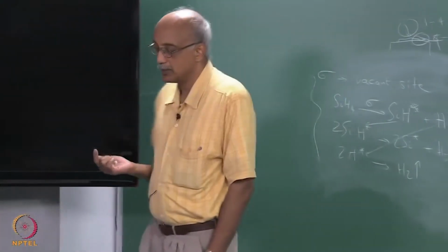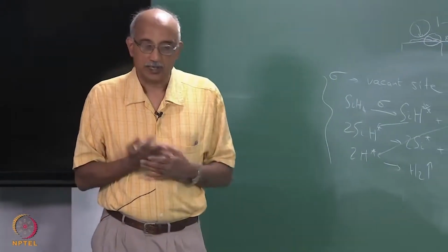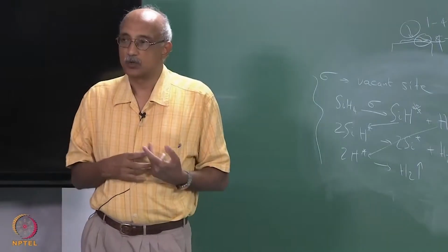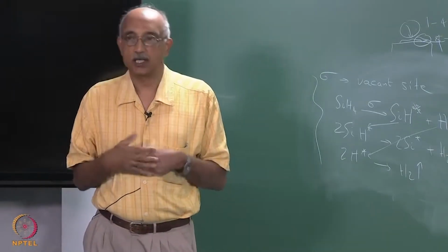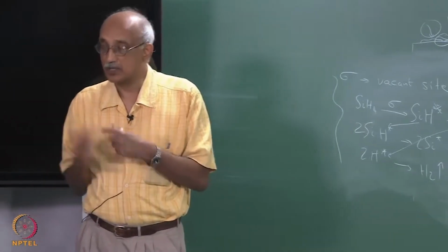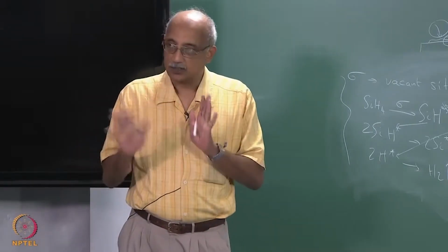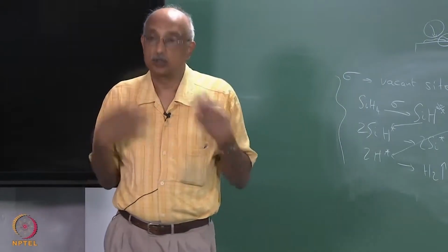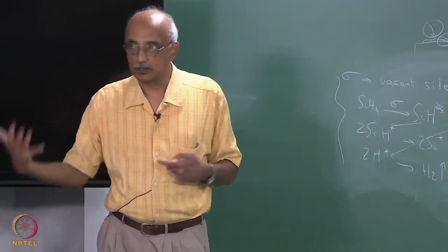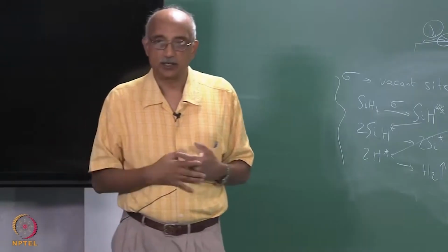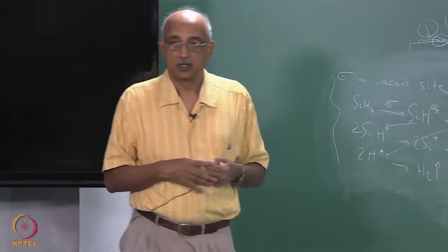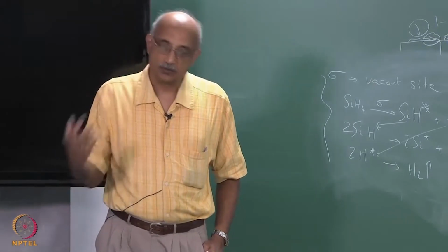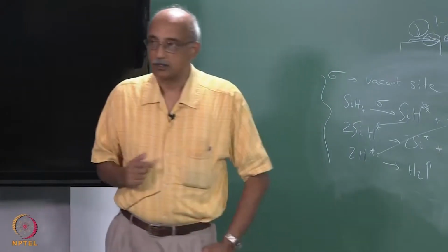And so depending on certainly the characteristic feature sizes in your product, you select the length scale that you want to focus on, and based on your selection of length scale, that decides your time scale. Ideally that is the approach. You should not make the decision of which aspects to focus on based on your capabilities, but rather on what the product requirements are. What is the functionality that is expected of the CVD film, and how am I going to be able to capture that in my model. So that should drive your analytical methodologies.